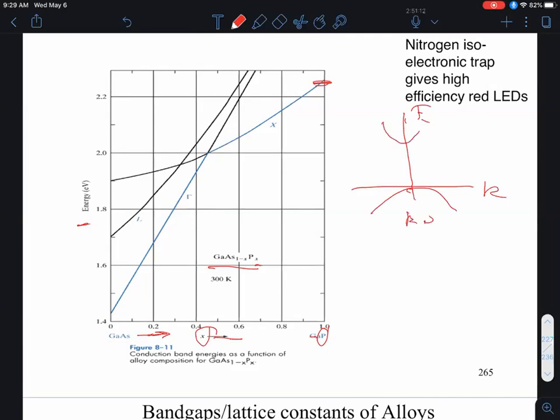If the conduction band minimum is at k equal to 0, that is known in shorthand as the gamma point. The minimum along the X direction, and this is not this x, X direction means the 1, 0, 0 Miller index direction, is known as the X minimum. And along the 1, 1, 1 direction, a minimum there is known as your L minimum.